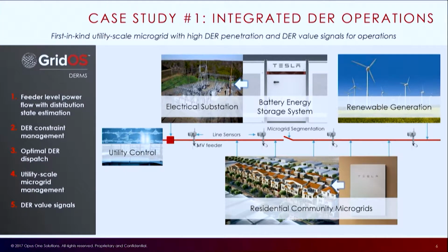So this is with a decent investor-owned utility on the East Coast around DER operations under high penetration, but going from just accommodating DERs to using them for resiliency, literally microgrid services on the feeder scale or utility scale. So there's 6 megawatts of wind on a very long distribution feeder. Reliability is low. Power quality is not ideal at all. And there is a mine in the middle of the feeder, while the wind farm is at the end of the feeder. And there's a good high net worth residential neighborhood scattered throughout as well.